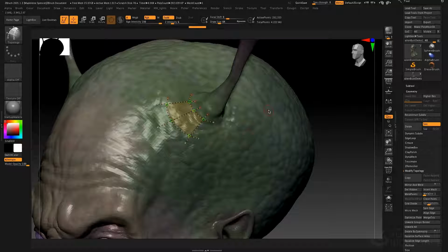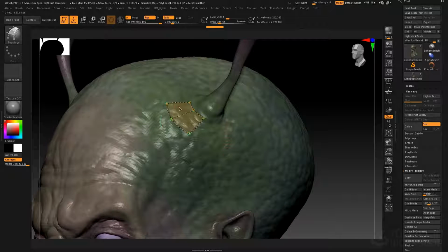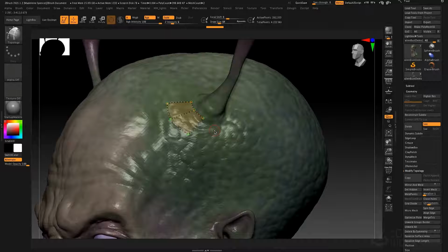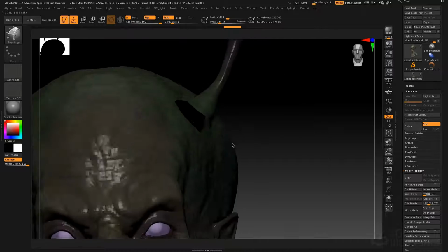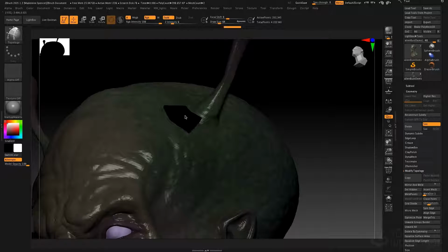Hold down the Alt key and just draw a curve somewhere else on the surface, and it will delete any of those hanging edges. So now I have a preview mesh. How do we turn this into geometry? If I hold down the Alt key and click on the model, it's going to mask the model and then show me the mesh it's going to generate.